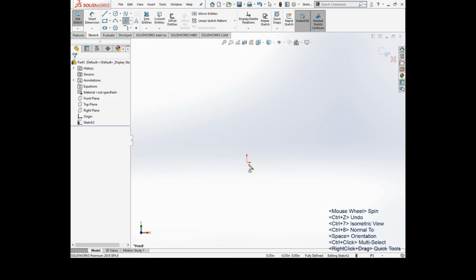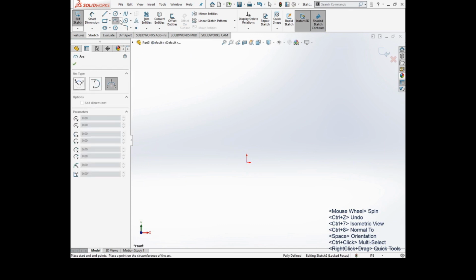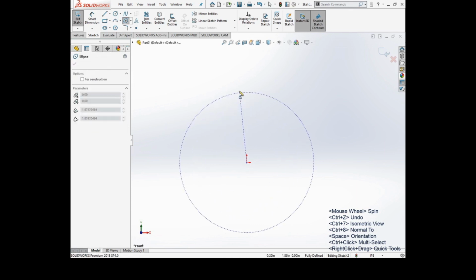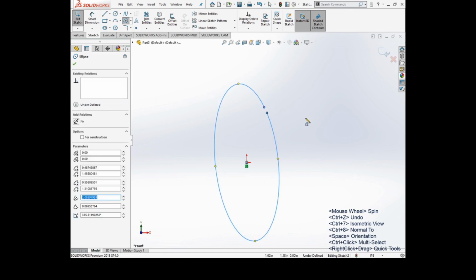Partial ellipse is like a section, a center point arc, where you don't get the entire ellipse, or you don't have to have the entire ellipse. You create your ellipse, and then you draw. So if I want everything but that little gap there, I could have that.